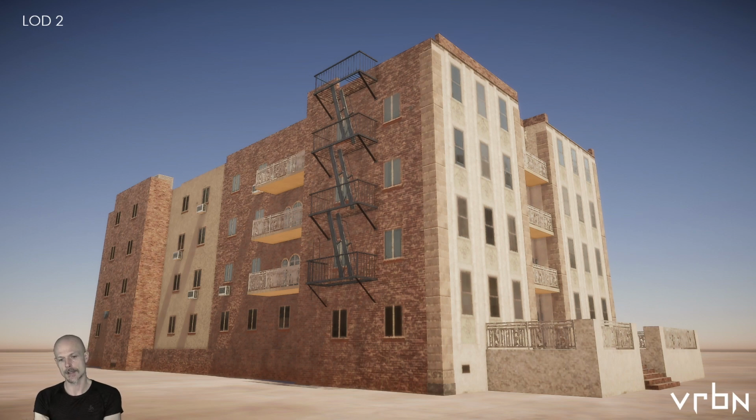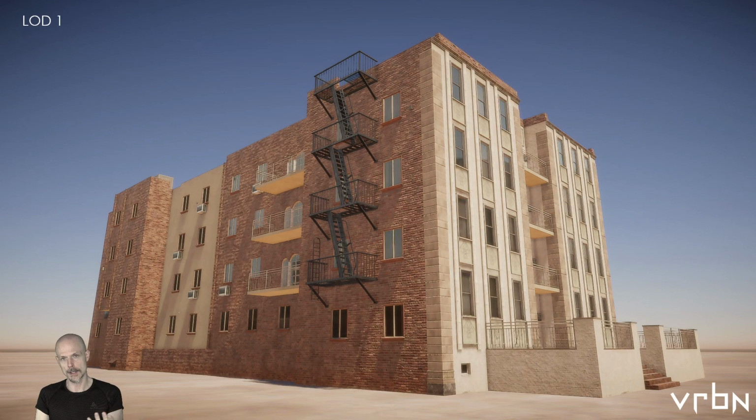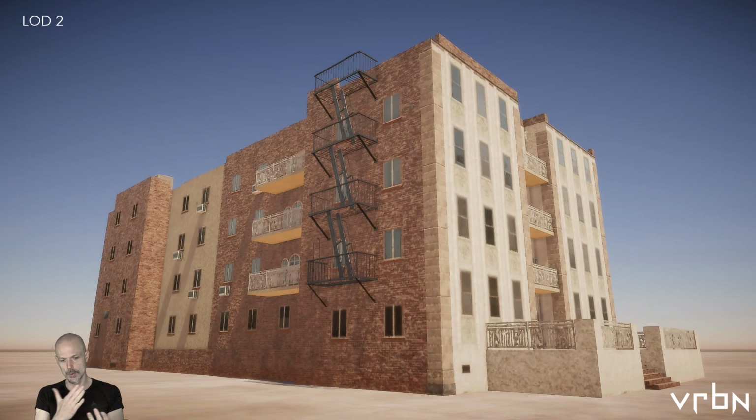And now considering that you have, for example, a complex interior that you're showing, we saw the bicycle before, right? You have to absolutely make sure that there is no jumping in the look, or no pop basically, in the look of what you would see in the high LOD, let's say LOD 1, to the lower LOD. So all the crunching together, all the merging of the materials into lower LODs of a system that is fully parallax occlusion capable, that's a huge technical challenge, right? And why are we doing this? Well, because we need to do it for all of the LODs. All right, let's move on from LODs.